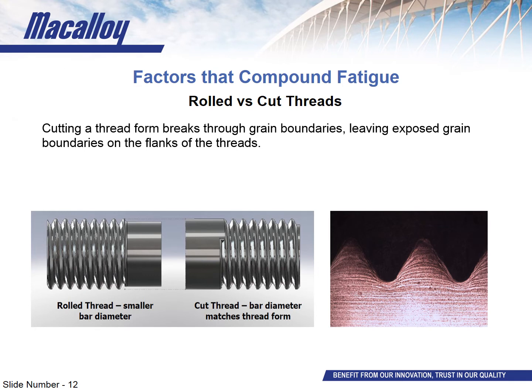In doing so, the tool is breaking through the grains of the steel and leaving exposed grain boundaries on the flanks of the threads. This is an issue in fatigue applications, as these exposed grain boundaries are areas that cracks can initiate.